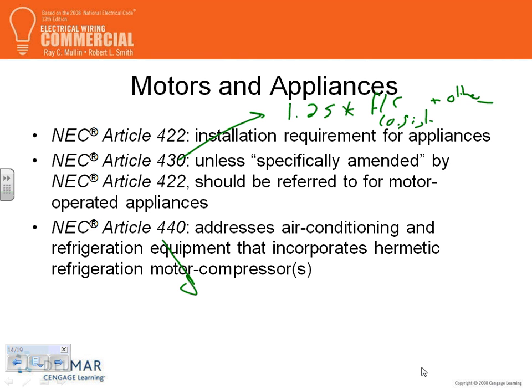For appliances, if it's a continuous load, it's 1.25 times the full load current of the appliance. So we added all this stuff, if you guys remember. Especially the motors and the HVAC equipment. Motors, 1.25 times the largest, plus all the others. We added them up. HVAC equipment, we looked at the heat and the cool, and 99% of the time in Minnesota the cool will be the largest, because the way we heat homes is natural gas. I don't know about other states, but at least here, 99% of the time your cooling is going to be the largest because of chillers, you know.